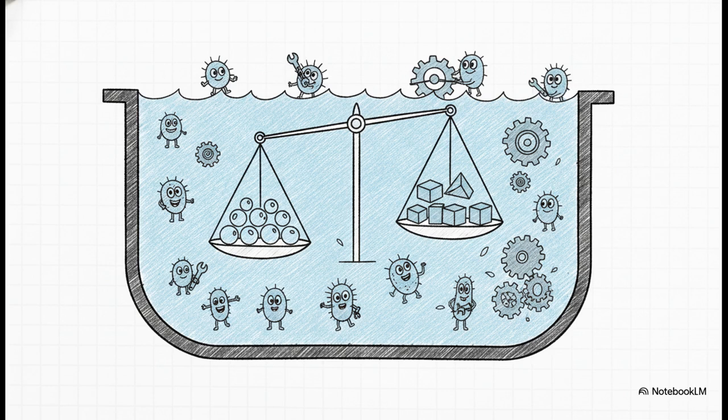But what if the culprit is a massive municipal or industrial wastewater source? Well, you can't just plant a tiny buffer strip and call it a day. For the big jobs, we rely heavily on optimizing microscopic biological processes. We're using nature's own engineered mechanisms here, specifically a 1-2 punch of nitrification followed by denitrification. To make this work, we have to stabilize the incoming water, the influent, to prevent massive, unpredictable nutrient spikes from totally overwhelming our beneficial bacteria. It's a highly delicate balancing act, meticulously controlled by managing oxygen and carbon availability.